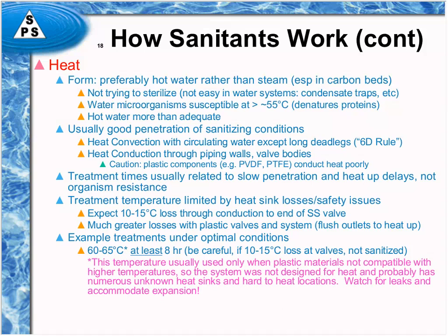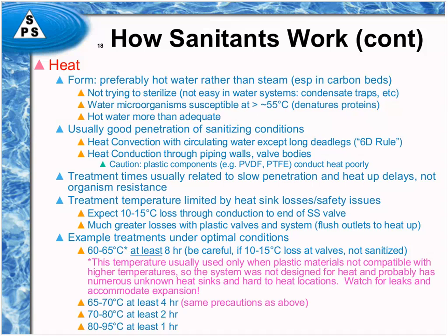And coupled on top of that, it's got to go for a long time to penetrate in areas that were never intended to be penetrated by hot water. Keep in mind that these systems probably also aren't insulated, and so you're going to have tremendous heat loss associated with this. So just be careful with this approach, especially in a system that wasn't designed for heat.